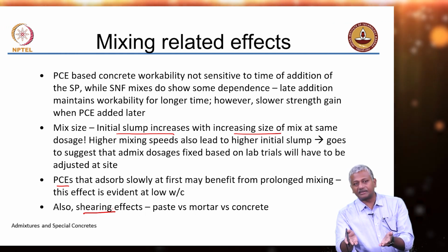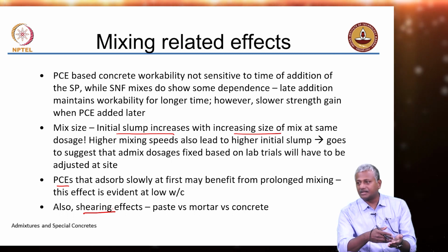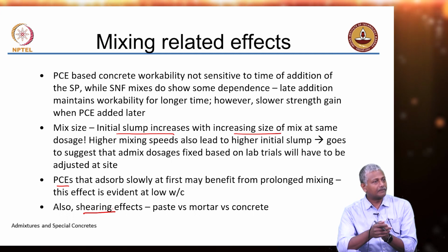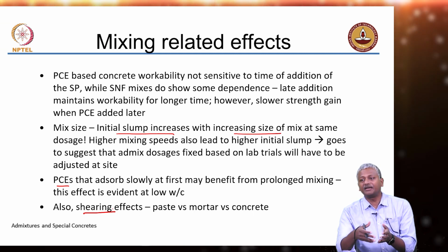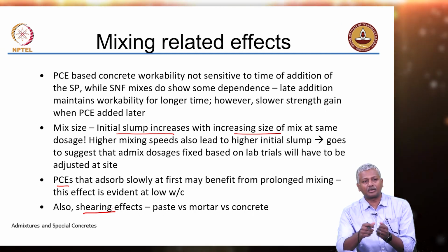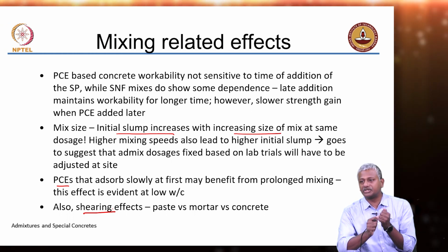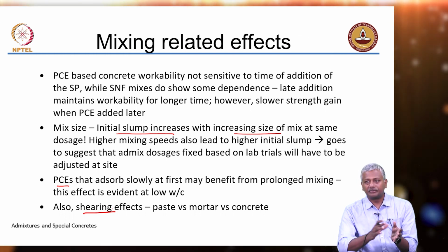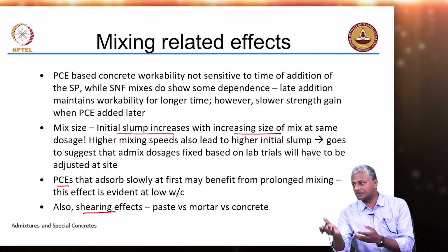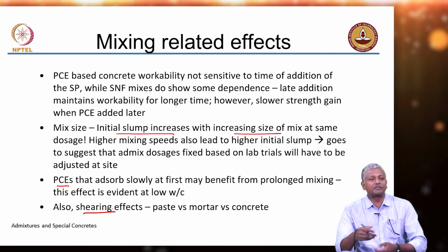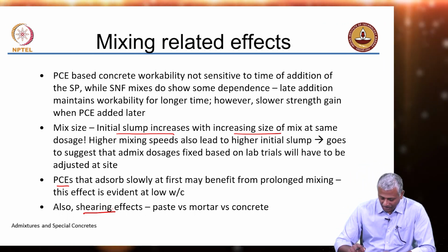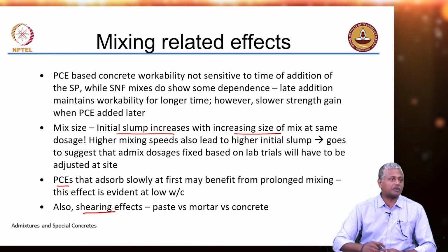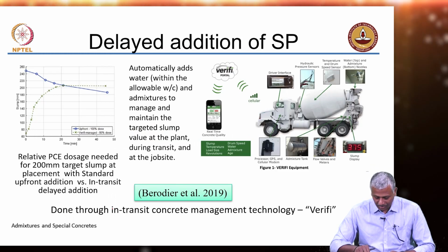Incidentally, it turns out that the saturation dosage estimation from the paste does produce a fairly good quality concrete. That is what we saw earlier, right. But your mixing depends a lot on the presence of the aggregate. There is better shearing, there is better mixing possible when aggregates are present in your system. So, when you design paste versus mortar versus concrete in the lab, make sure that the mixing process is adequate. Okay. So, all these are complications which we have to work out well in advance before we sort out this problem of compatibility on site, right.